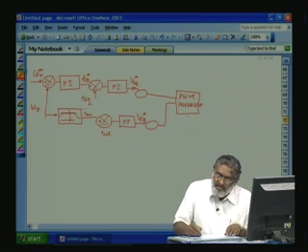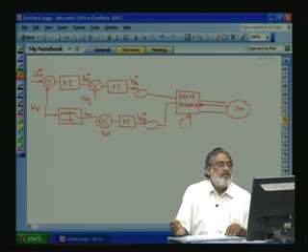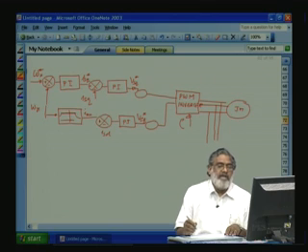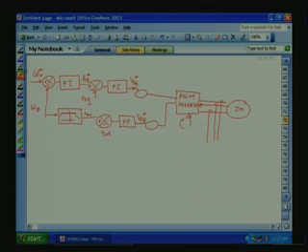So, VSQ, VSD we got it. Here we require the rho also. This will go to the motor, induction motor. Okay. From the motor we will sense the current. All three sensors are not required because IA plus IB plus IC is equal to 0. So, 2 current sensors are required. For clarity we have put 3 here.